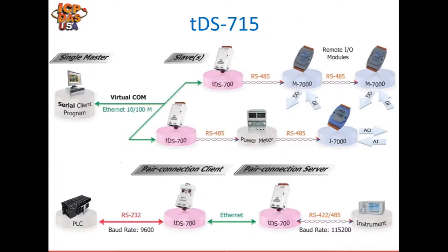Here's an example of the TDS application. Note on the left side the PC running the virtual COM port. So devices connected to the top TDS 700 series, for instance, would be connected to devices considered COM1, and the TDS at the bottom or in the middle would be connected to COM2 for the power meter and for the i7000 series. And each of the different TDS or COM ports would be communicating in different protocols. The top one being our Modbus RTU modules, the bottom one using either just standard RS-485 serial strings or our